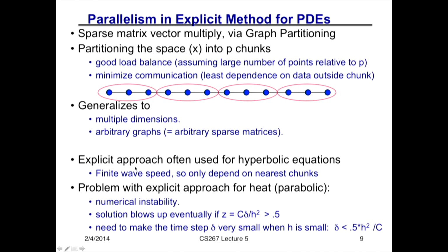And so let me just do a simulation. I'm going to solve the heat equation. I'm going to use the method that I just showed you. And this is called the explicit method. Each update is going to be a sparse matrix vector multiply. And you'll see on the next slide that it's actually a very bad numerical method. It's going to blow up. So even though I did all the calculus right and I showed you that, if I try to take a time step that's not incredibly tiny, the solution is going to make no physical sense whatsoever.